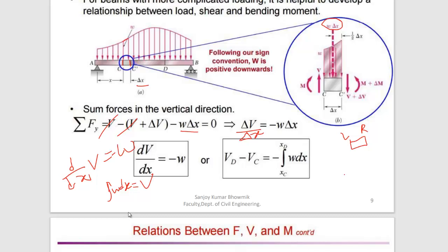So if theory says that differentiation of the shear, we can get the load, then integration of load can give us the shear. So what does it mean? If you take the area of a load, you can get the shear value. This is the simple technique.